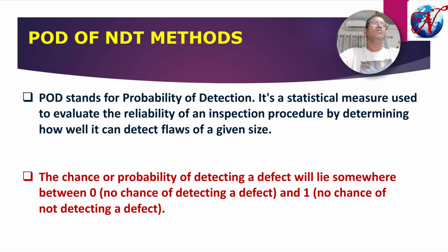But if we consider ultrasonic inspection, then defects like transverse crack or lack of sidewall fusion are perpendicular to our ultrasonic beam, because we are able to produce the sound beam and transmit it into the material at a definite angle, such that those defects, that is transverse crack in the weld or lack of sidewall fusion, which originate in a definite plane, are perpendicular to the ultrasonic beam, and there is a maximum probability that you can identify those defects.